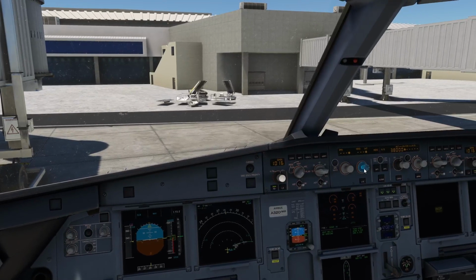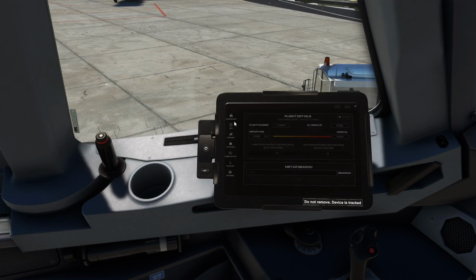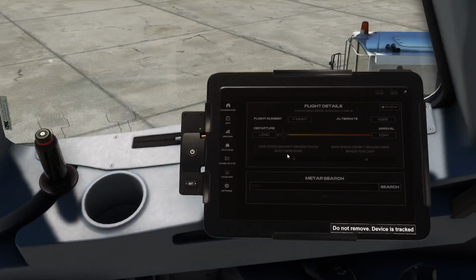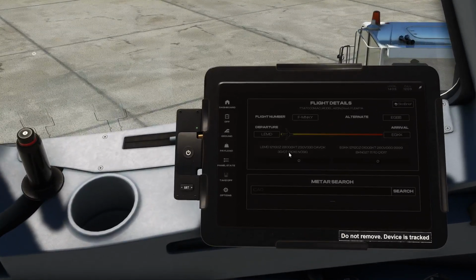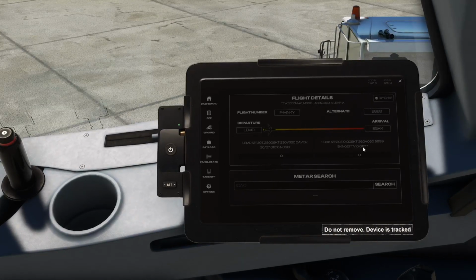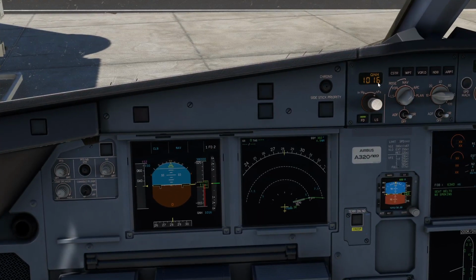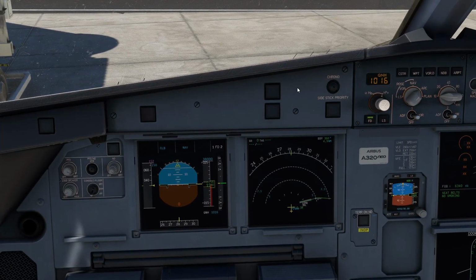Okay, so say your altitude, I've already done that, that's what I need today, 38,000, and leave these two alone. Make sure your QNH is set correctly. So if you have a keyboard, press B. If not, look at your METAR page and it should tell you, see on here, there you go, Q1016, okay, that's Quebec 1016. So then on here, when we arrive, it would be Quebec 1017. So that's what you'll need for your QNH, okay? So that's all that's set.